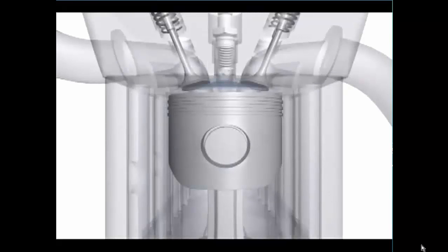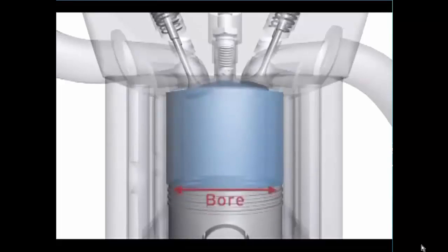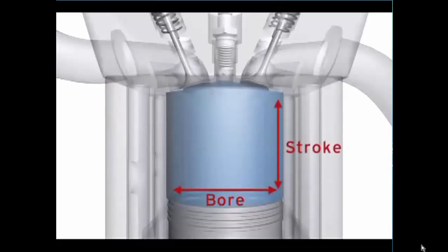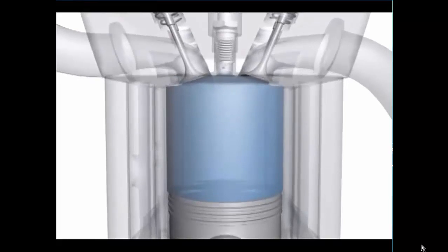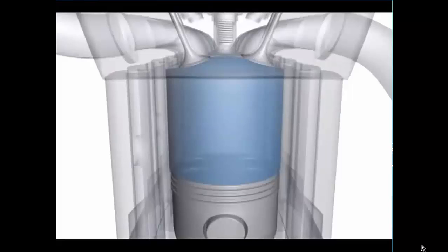Engine displacement is how the internal size of an engine is described. It's measured as the cylinder bore times the length of the piston stroke. This is multiplied by the total number of cylinders and is usually expressed in liters or cubic centimeters.